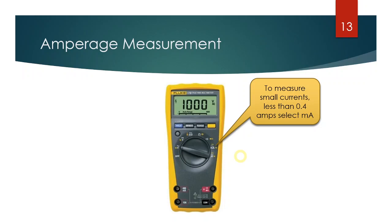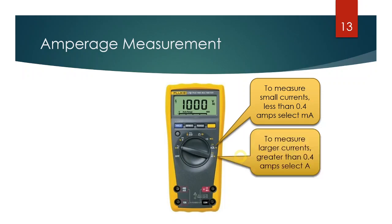When we get into electrical applications, we'll be able to quantify how much current that actually is. So if we're measuring smaller currents, we're going to use that setting. And if we're using larger currents, larger than that 0.4 amps, we're going to select the second one there.